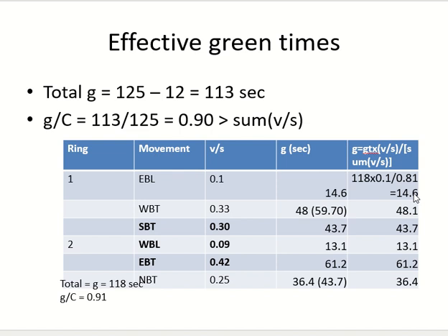Yellow or red and green. So I know effective green time. Effective green time is the actual green time plus yellow time or red time minus lost time.